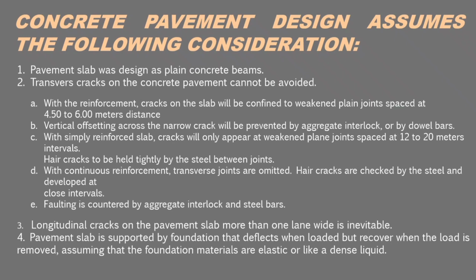D. With continuous reinforcement, transverse joints are omitted. Hair cracks are checked by the steel and develop at close intervals. E. Faulting is countered by aggregate interlock and steel bars.